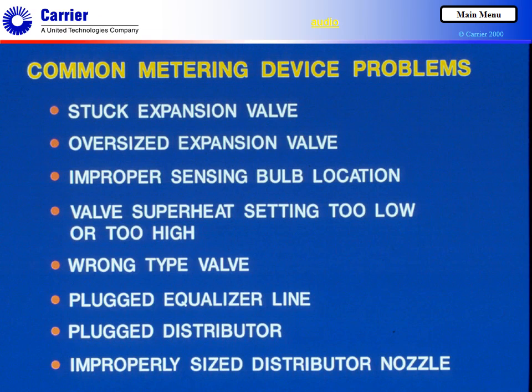Unattended problems in the metering device are likely to result in an eventual compressor failure. If the service technician replaces the compressor without identifying and correcting the root cause, the compressor is sure to fail again. Repeat compressor failures are a major problem in the air conditioning industry. They result in unhappy consumers as well as tremendous unnecessary cost in labor and parts for dealers and manufacturers.